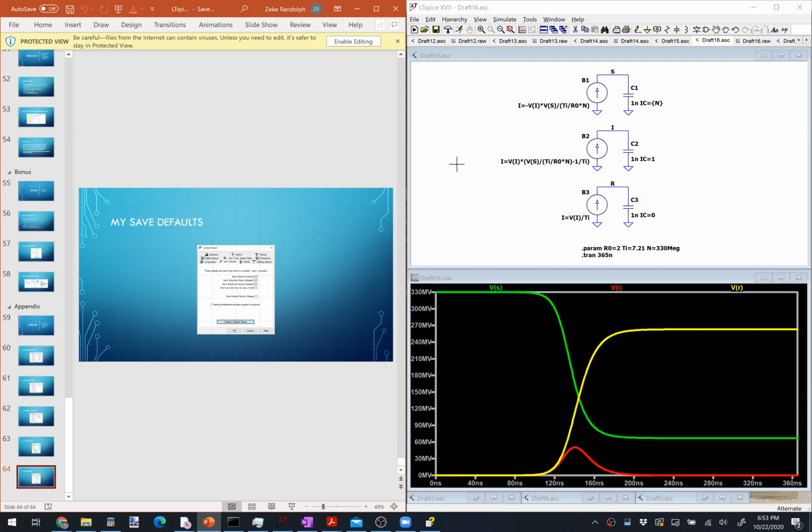And oh, absolutely. Yeah, it's a great tool. One of the things I'll mention though, is if you're a beginner to SPICE, you open up LTspice and then you're like, well, how do I draw a schematic? Or how do I draw a layout? And you'd be somewhat disappointed to find that LTspice really isn't the right tool for drawing a circuit layout, or for dropping a microcontroller down and specifying component packages, say an 0805 resistor or a 1206 resistor or any of that stuff associated with the physical construction of the circuit.